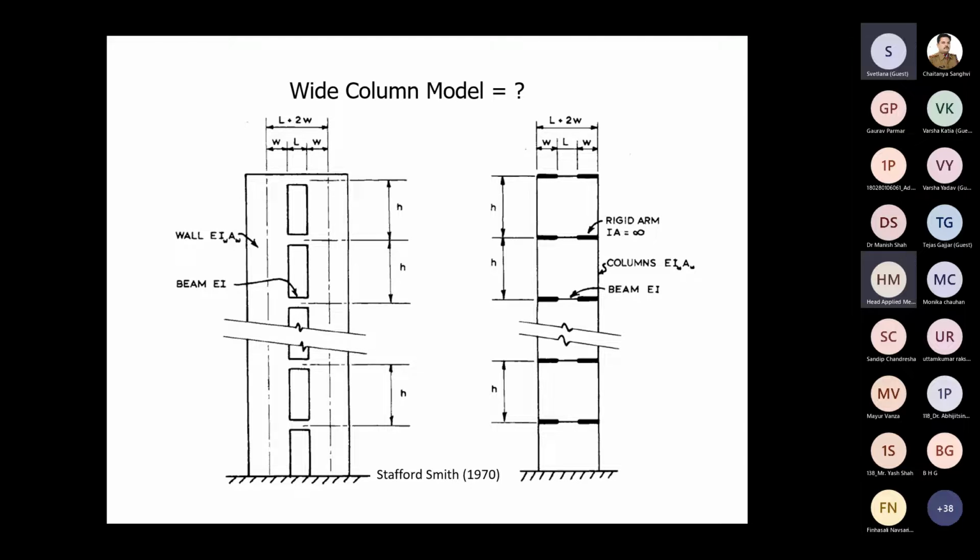Later on I will talk about how to simulate this high rigidity, what are the ways that at least I use in modeling, or I recommend to the students. But right now let's leave it at that: one is infinitely rigid. So you can see the moment of inertia times area is infinite, whereas for the beam element, we call this the rigid element and the beam element, it is EI, the exact properties of this element, and it's entered with those properties in the model.